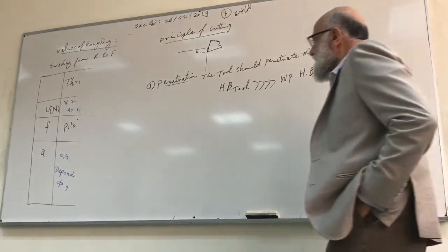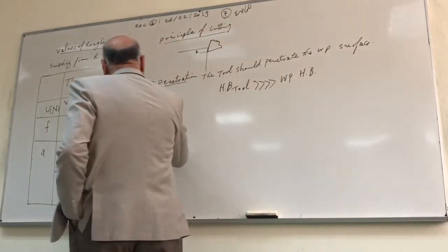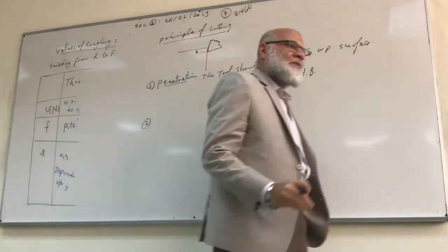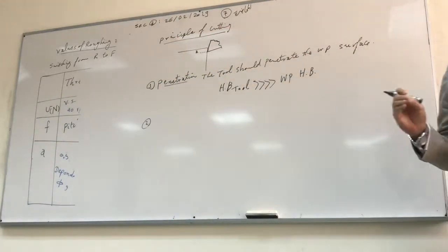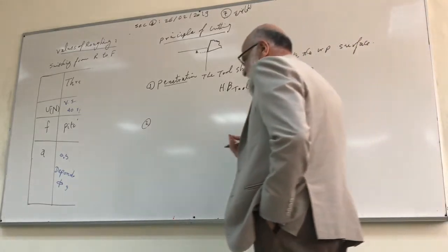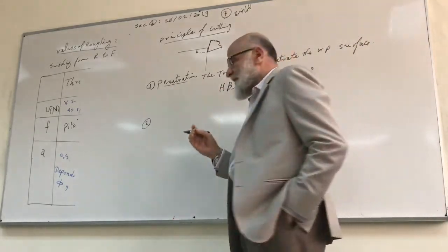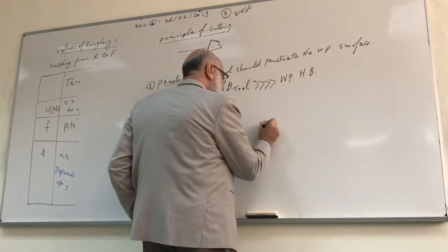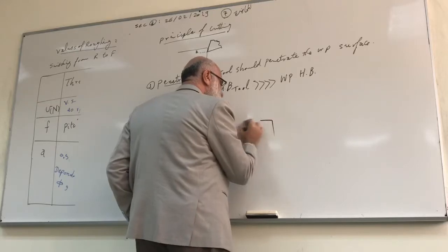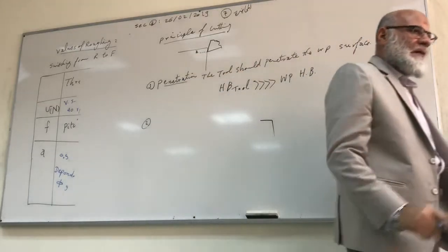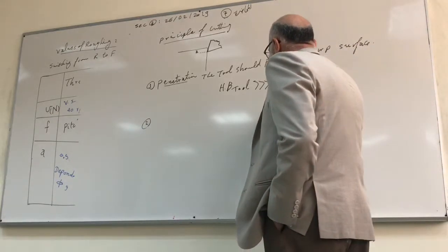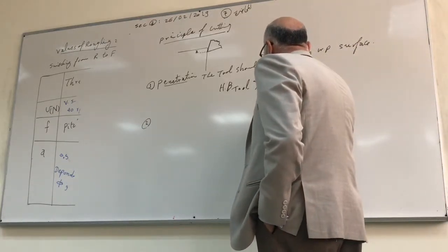Okay. Number two, what will happen after a while if the tool penetrates the workpiece surface? After a specific, very short time, a moment, what will happen, brothers, is that some amount of the material will be separated, heated and compressed in front of the tool, like this.